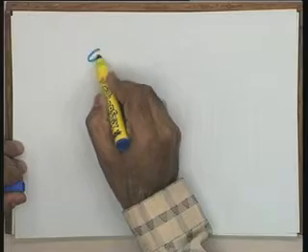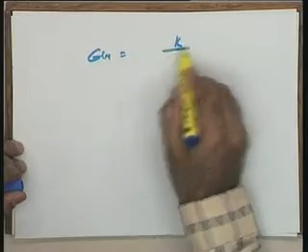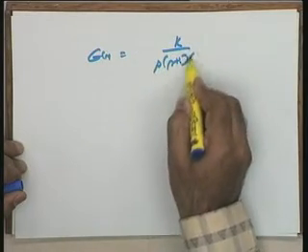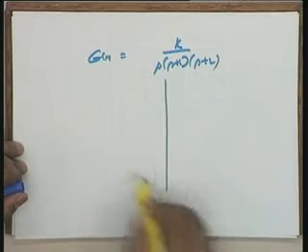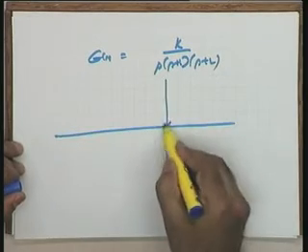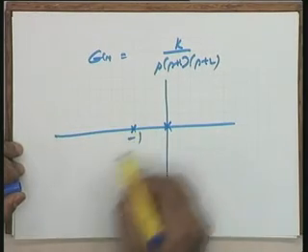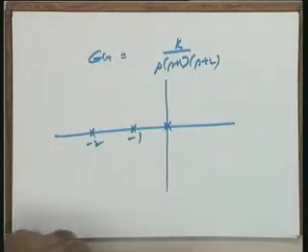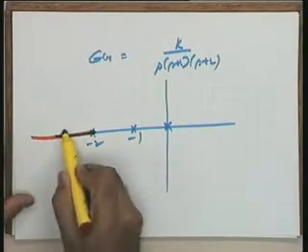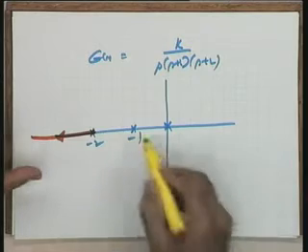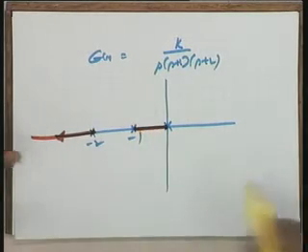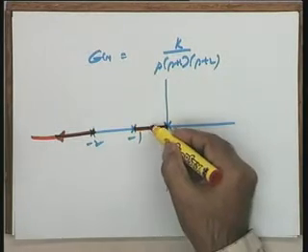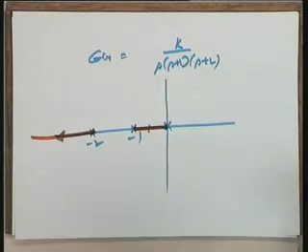Lastly, you will recall an example we had taken, G(s) equal to k over s into s plus 1 into s plus 2. For example, take it this way. So, s is equal to 0, s is equal to minus 1, s is equal to minus 2. You apply your rules, you will find that this is one branch going to infinity. You find that this segment lies on the root locus, and hence there has to be a breakaway point.